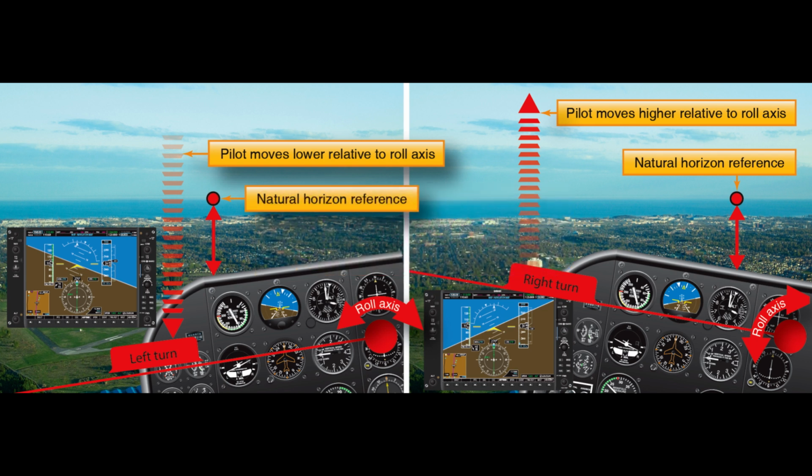For medium bank angles, the ailerons and rudder should be neutralized. Steep bank angles require opposite aileron and rudder to prevent the bank from steepening. Back pressure on the elevator should not be relaxed as the vertical component of lift should be maintained if altitude is to be maintained. Throughout the turn, the pilot should reference the natural horizon, scan for aircraft traffic, and occasionally cross-check the flight instruments to verify performance.